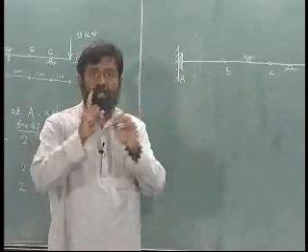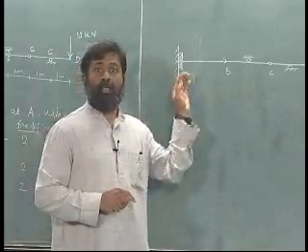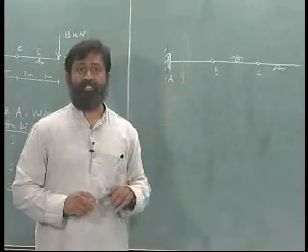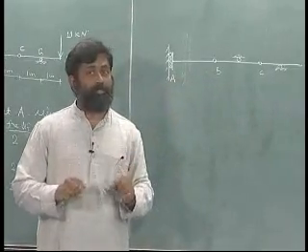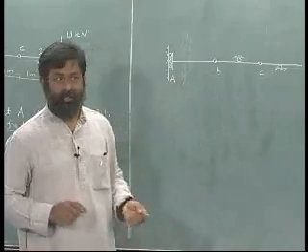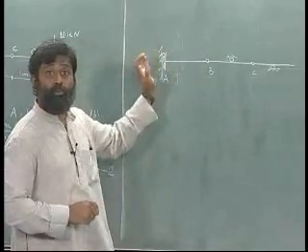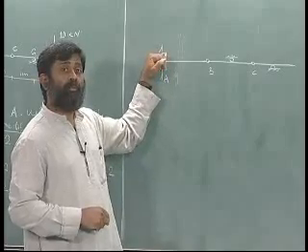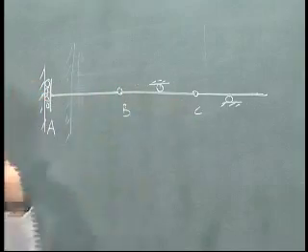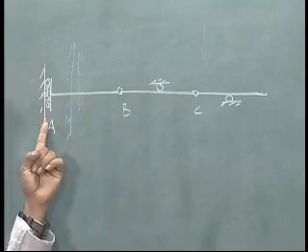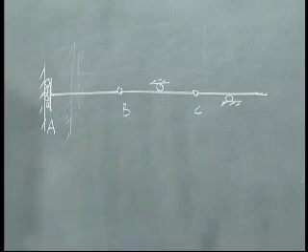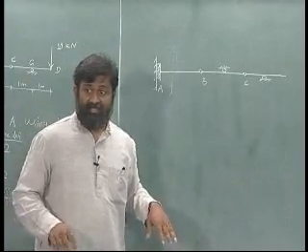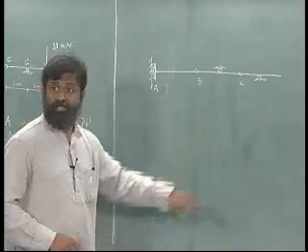Okay. The only condition I have to impose is a kinematically admissible virtual displacement. For example, I can't opt to make a rotation over here, I can't say okay I will put a virtual rotation and find out. Please remember it has to be consistent with the support conditions as well as the notion of rigid body.